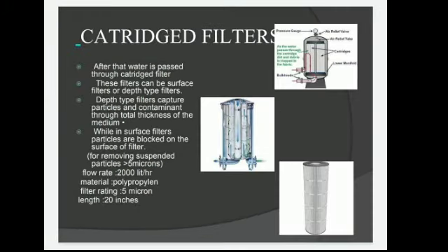Cartridge filters. After that, water is passed through a cartridge filter. These filters can be surface filters or depth type filters. Depth type filters capture particles and contaminants through the total thickness of the medium, while in surface filters, particles are blocked on the surface of the filter.